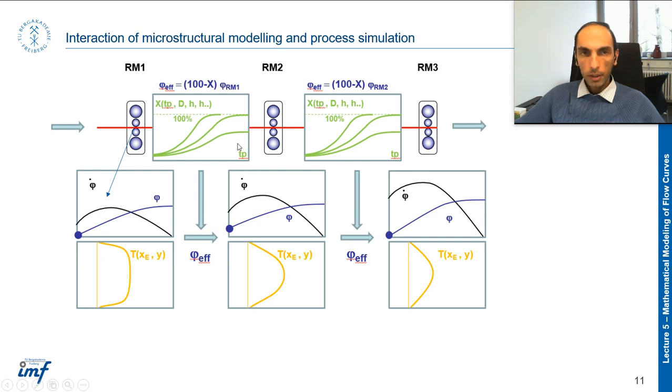So if you look into the rolling gap here, exactly here, then you can find that the value of strain is not constant, because when the material goes between the rollers and proceeds step by step, the applied strain increases and it becomes plateau at the end.